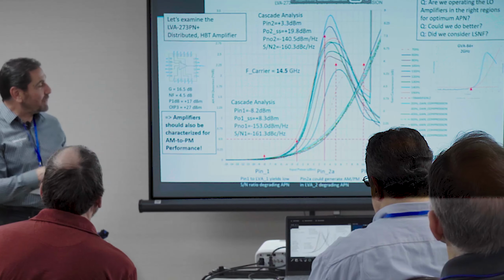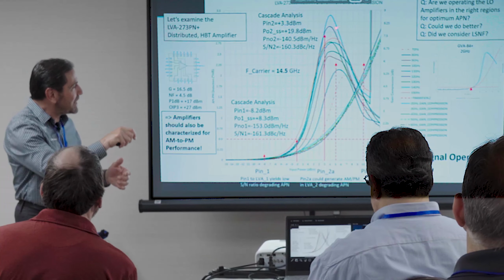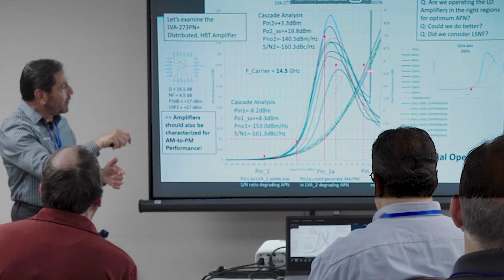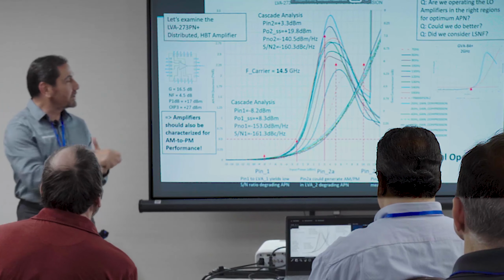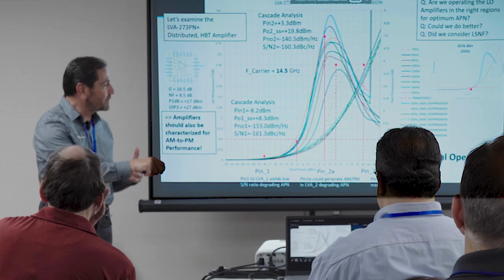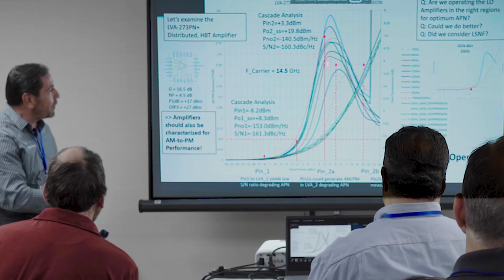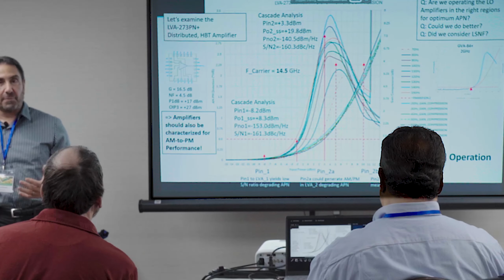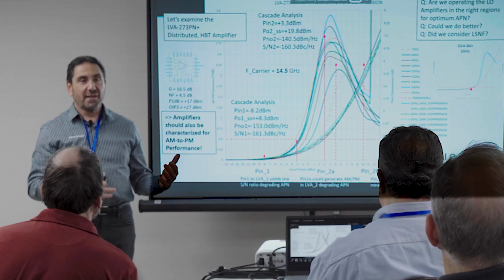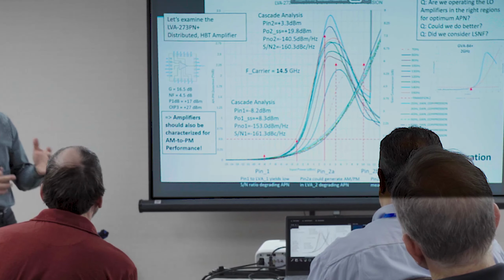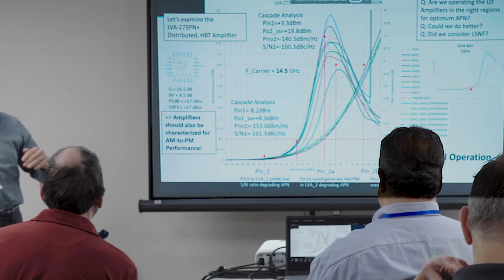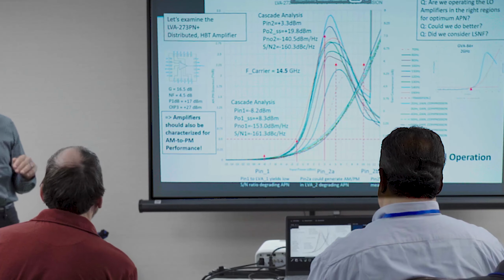Amplifiers will have this kind of a characteristic shape up to about here. What happens in this region is amplifier dependent. They don't all come down again. Some stay here, some come down. They don't all get worse with frequency. Some get better with higher frequency. So there's really no general suggestion I can give you. You have to measure this because each amplifier is unique.